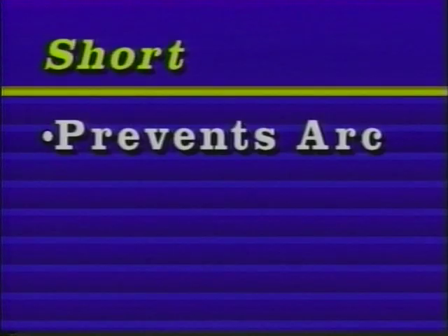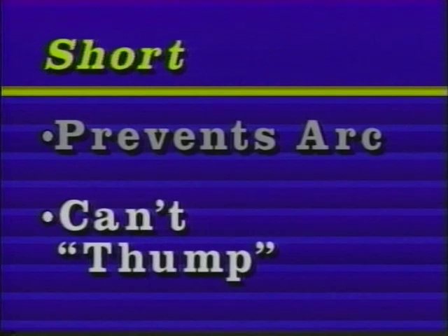If the fault is a short, measuring a few ohms, the conductor is probably fused to the neutral, and again you may have to burn the fault open. The thumper will not be able to arc from the conductor to the neutral if they are shorted together, and without an arc, the thump or ionization of air cannot take place.